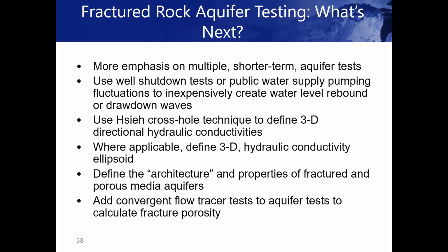So that's number one. Also, if you're not careful, and that's why I showed that one jug of clean water, it's my practice, after we inject the tracer, to then typically inject maybe 2 times as much clean water back in to make sure we've got most of that tracer out into the formation. So that's a factor too. You get some mass that just hangs around the well bore and maybe more slowly leaks out, and that causes, I think, some of that tailing.